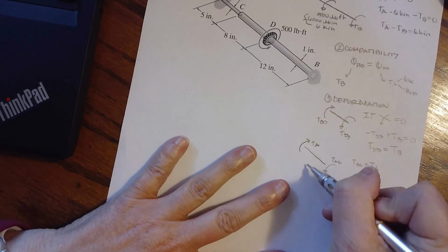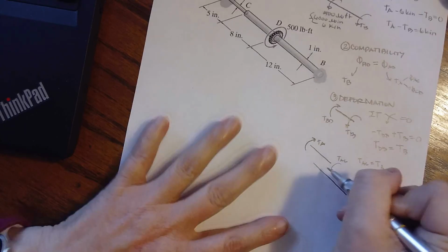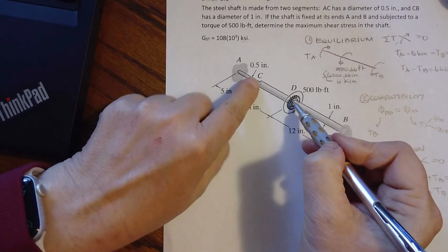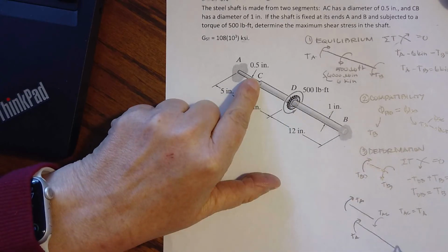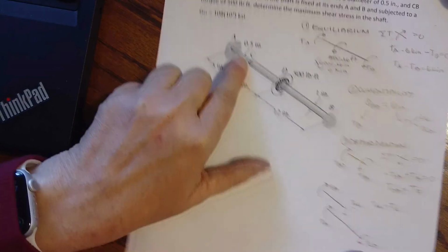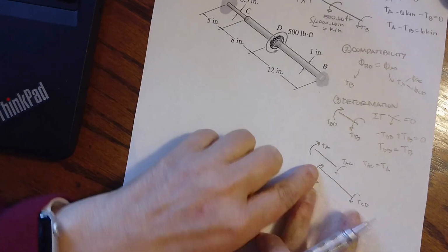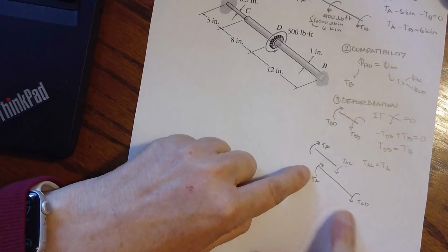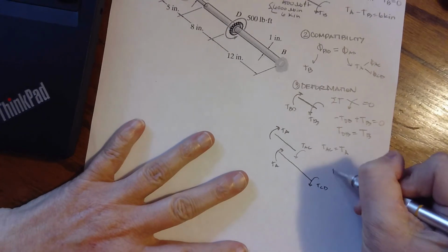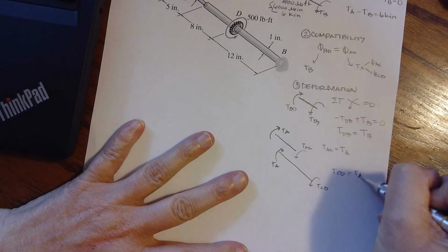Okay, now I need to come through, and I have the torque at A, and I'm coming through here between C and D. So now we're cutting internal here, and I'm going to have the torque from C to D. There are no other applied torques here, so it's continuing that same torque, but I have to cut it in 2 places because of my geometry. So again, the torque from C to D equals the torque at A.